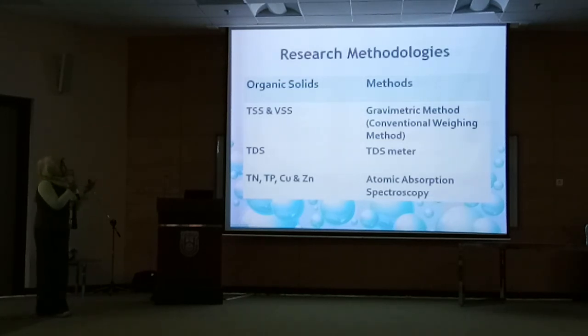TN, TP, copper and zinc are nutrients for microbes, so they are reasons water can be polluted. We used the gravimetric method for TSS and VSS, a TDS meter for TDS, and atomic absorption spectroscopy for TN, TP, copper and zinc.